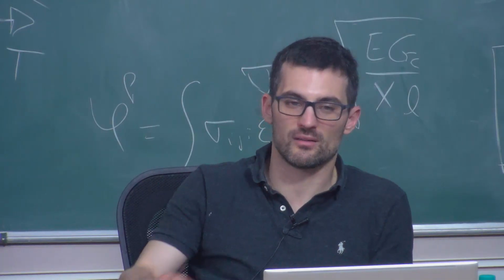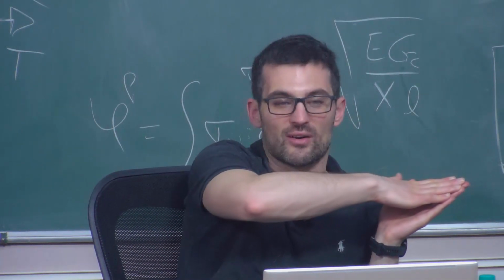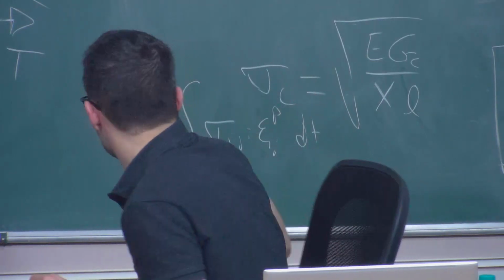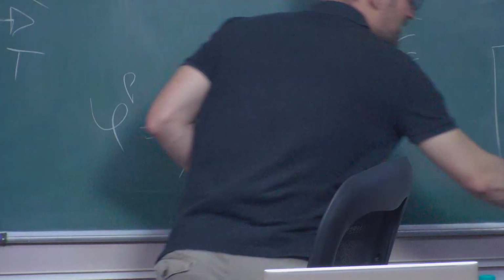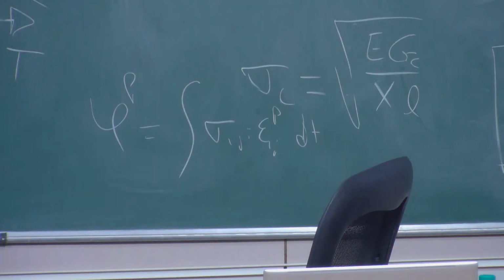They did some diffusion simulations ahead of a crack, and they saw that, first of all, the quantities that you get at a steady state, so they basically plotted stresses ahead of a crack using conventional plasticity, but your material model doesn't really matter that much. You get this hydrogen concentration. Normally, because it depends so much on the tensile stresses, on the hydrostatic stresses, the hydrogen concentration kind of follows your stress distribution.